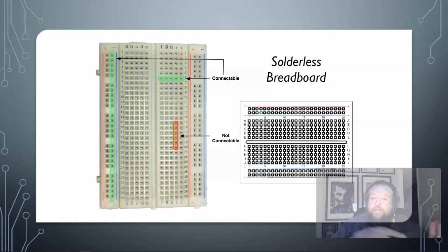Later on, we're going to have the Arduinos, and the Arduino handles some of the power and negative there as well. So you can really connect whatever wires you want, but it's a good convention that if you have your power source, you'll connect it to the line that's marked negative. For your power source here, you'll connect it to positive. These lines, maybe you'll have lines that run over to share to each other side, and then you start connecting things together. And that's just so that you're like, okay, I know that I'm using this for negative, I'm using this for positive, it's marked, and then everything else becomes clear after that.